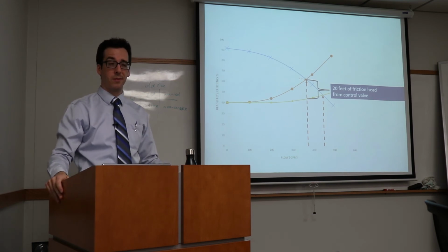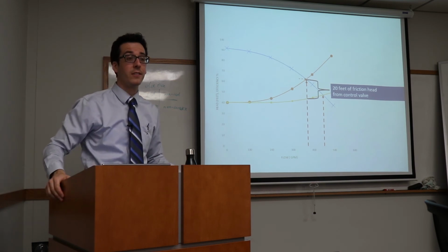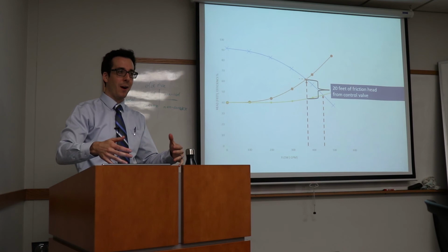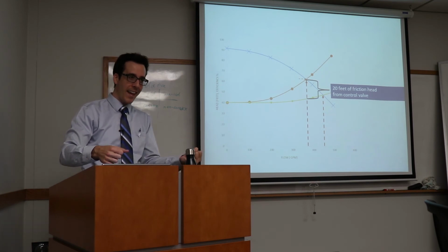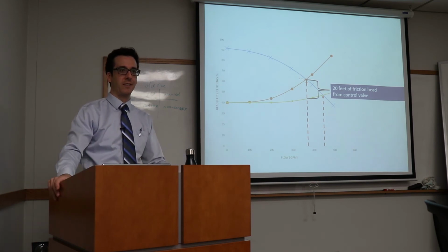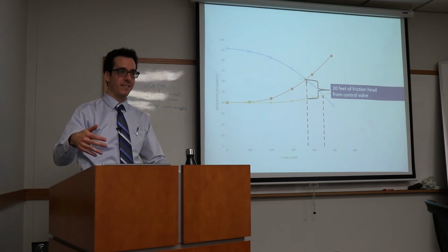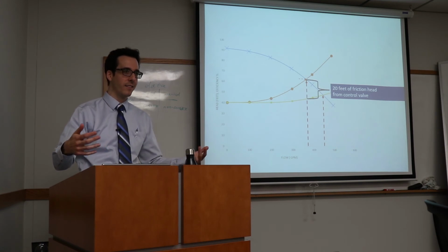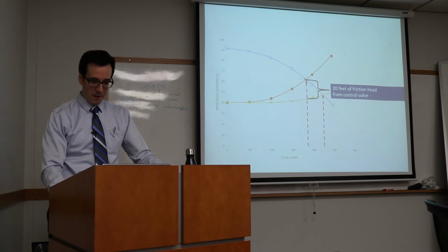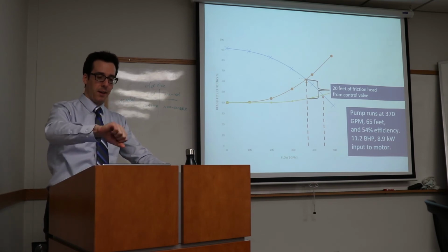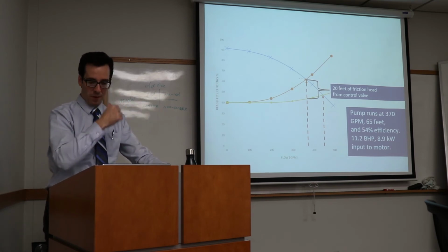Why is that bad in terms of energy efficiency? You're still using the same power. Right. You're putting in power, and then you're taking out power by adding friction, right? It's like shining a lamp on a solar panel, right? You're putting energy in, and then you're just taking energy out. It doesn't make sense. Okay, so by doing that, just by turning the valve, we bring it back to the design point.